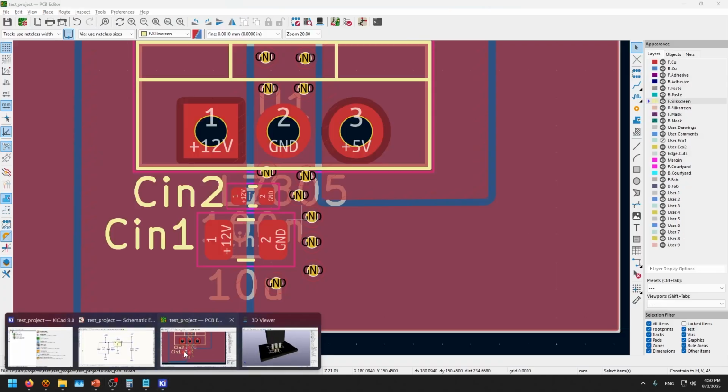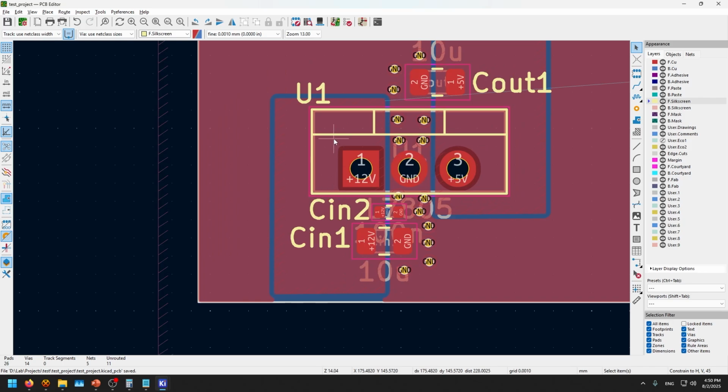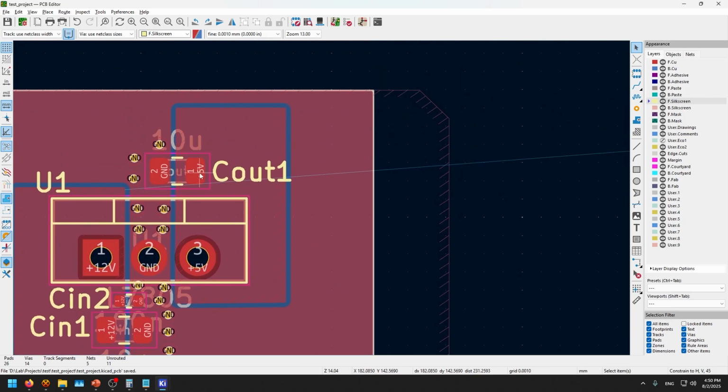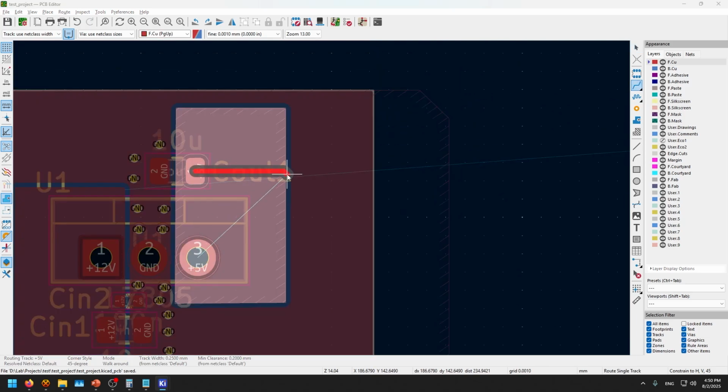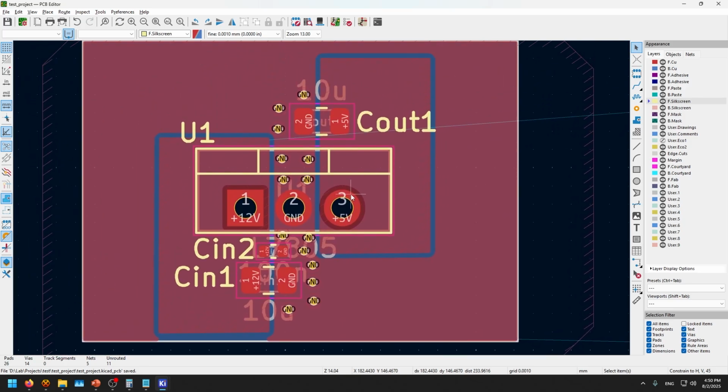If this is part of your circuit, you can basically route the 12 volts using the polygon to the source, and you can take the output either from this cap using a very short trace like this, or also extend the polygon pour to wherever you want to go.